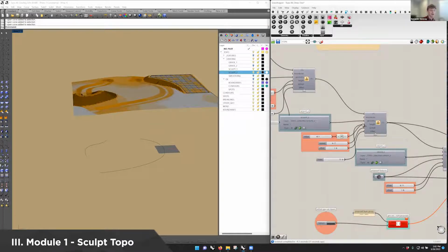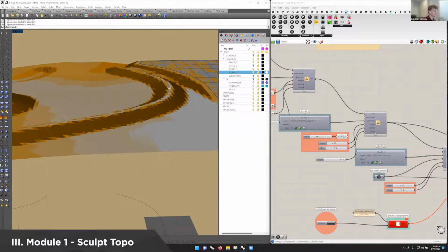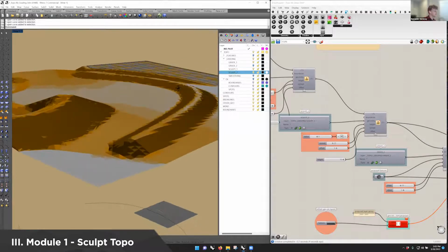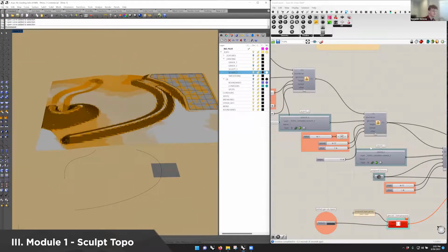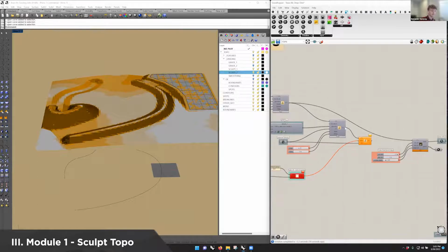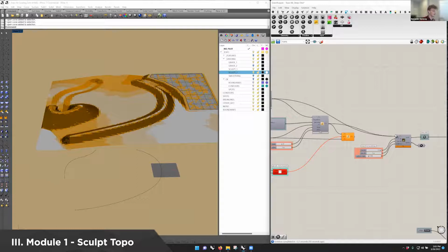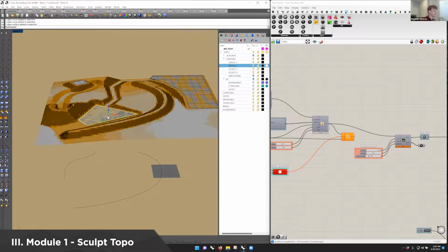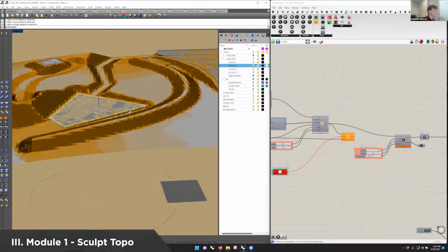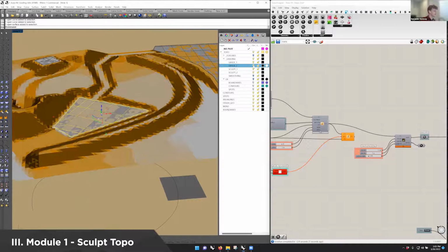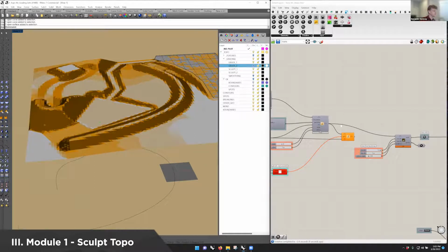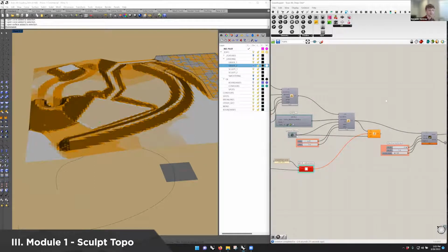If I want to make the height positive and create this big mound going through the site, I could change it to a +10 and create this nice berm coming across the entire site. And then the same with the grading: we've added another set of parameters of a 35 slope with a 5 offset with a different set of geometry. And what you're seeing here is this wonderful surface dropping things down. It looks like we're actually creating that path feature, but we'll talk about that a little bit later, probably, right, Chris?